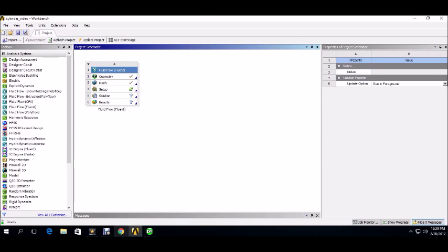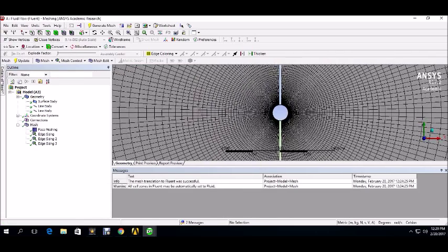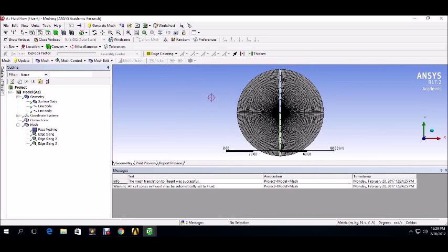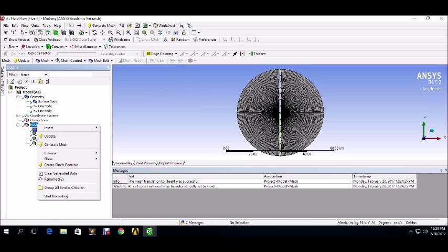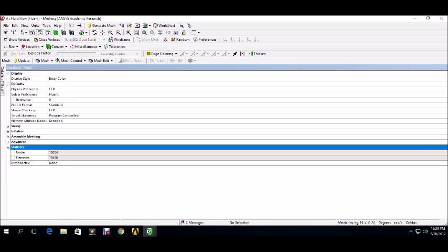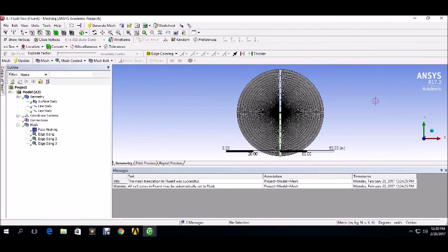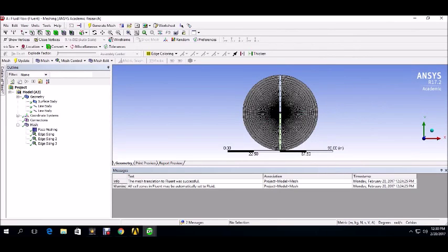All right, so once we finish this mesh, we can check to make sure it's right. So we can click mesh, and then once you click mesh, you can go here to this plus, expand the statistics, and you should have roughly this many nodes and this many elements. Once it looks like it's correct for you, then we want to name some of the boundaries in this